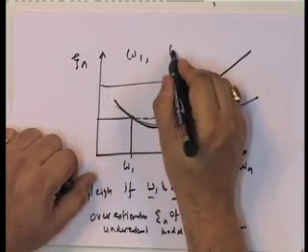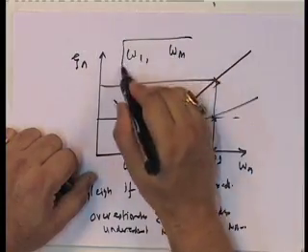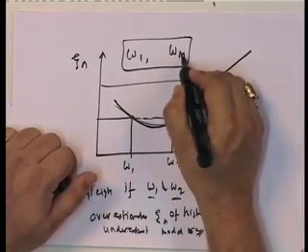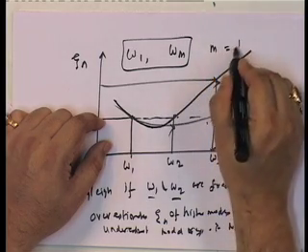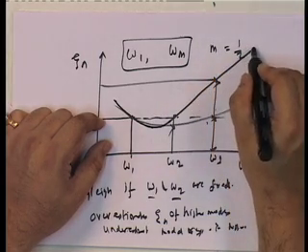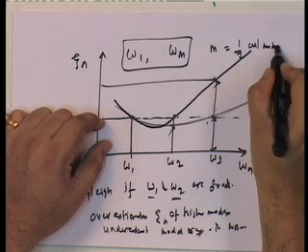Okay. So, you may say that look, I am underestimating a few, overestimating a few, which is why actually in a way Rayleigh damping has been used for so long. The reason Rayleigh damping has been used is that instead of omega 1 and omega 2, you actually take omega 1 and omega m. Omega m is not really omega m, actually this m is approximately about half of all modes that contribute.